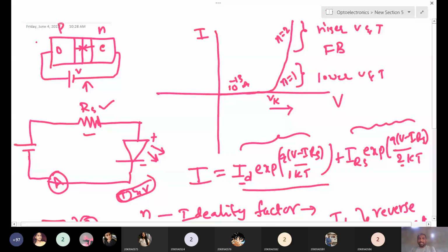Varying the voltage, we measure the current. From there we analyze this curve and can estimate the defects, where our device is having a problem. We rectify that problem while fabricating the device, so that we make a good device and get good output.